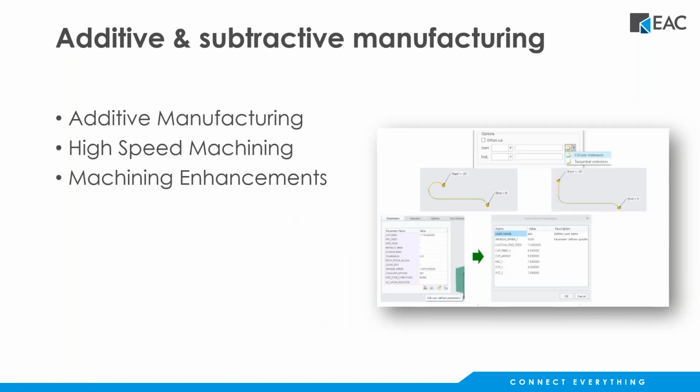And then some other general machining enhancements. We have added flexibility to define the NC toolpaths. We have the ability to eliminate a limitation of using only existing CL commands in Creo NC. And we have improved cutter compensation support for profile passes in the HSM rough capability.